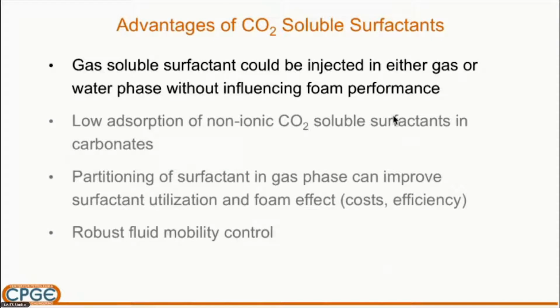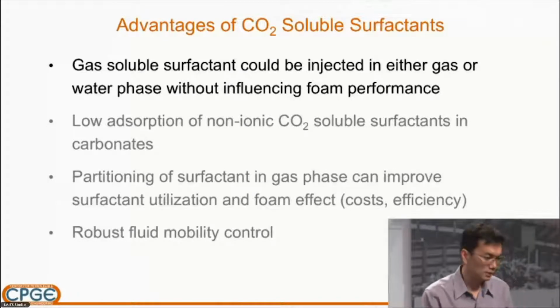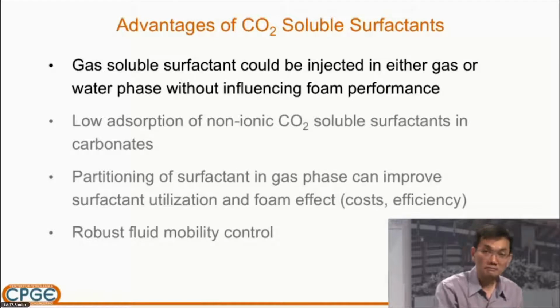Now we took foam to the next level, which involved the use of CO2-soluble surfactant, which I studied back in 2008, when I had an opportunity to work with Dr. Keith Johnston right here. He taught me about CO2-soluble surfactant, and we worked together to develop a novel foam concept. And there are several advantages of CO2-soluble surfactant. One is that the surfactant can be injected in either water or the CO2 phase, so it is going to be very beneficial for field implementation without influencing foam performance.